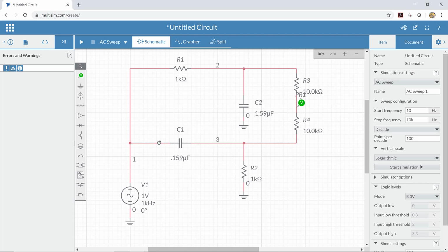Similarly, at high frequencies, the high-pass filter says yeah, that should go through, so it takes its end of the jump rope and goes up and down. The low-pass filter says no, it holds its end still, so the middle of the jump rope ends up going up and down halfway.